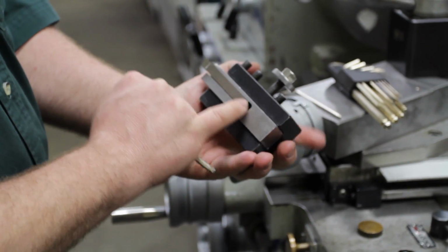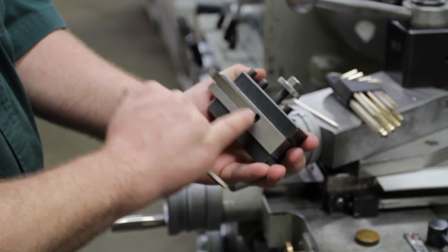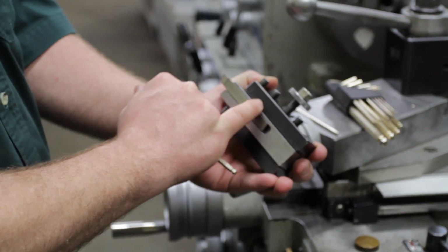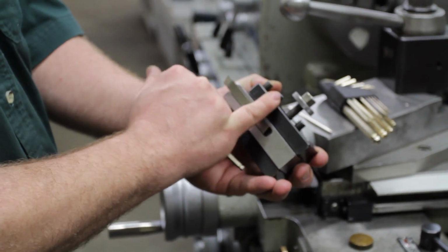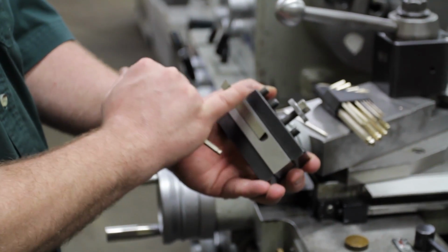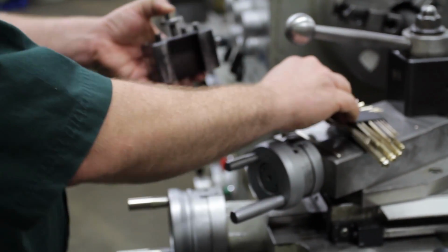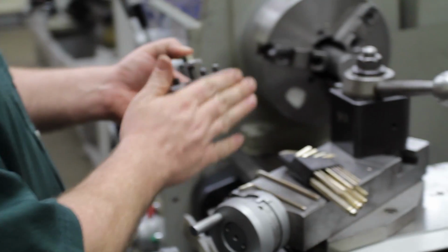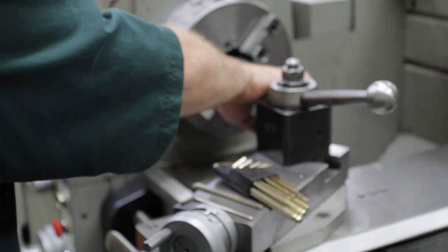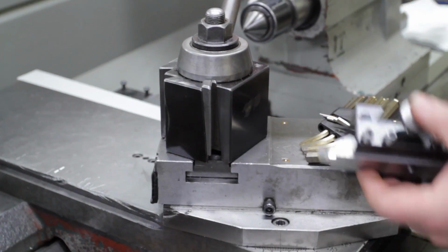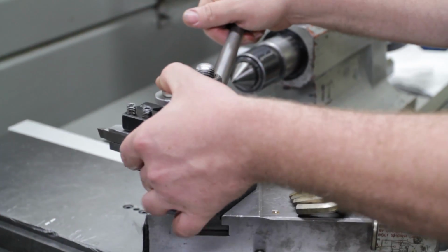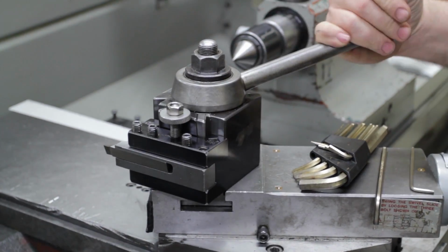So keep in mind, sometimes your tool bit's not all the way back in the slot. If there was a screw right over an open part of this tool holder, I would not tighten that screw. You would just tighten the two outside ones then. So you then put this on the dovetail tool holder. When you put it on there, you bring it down from the top, and this handle locks it tight.